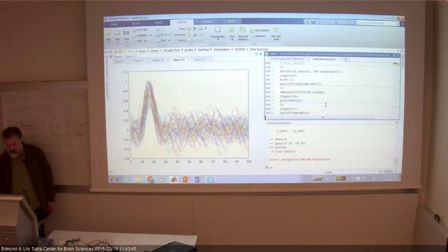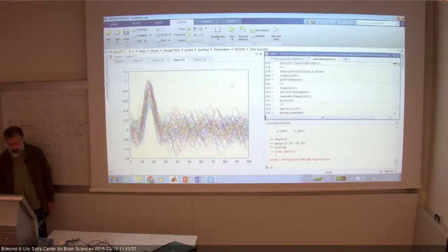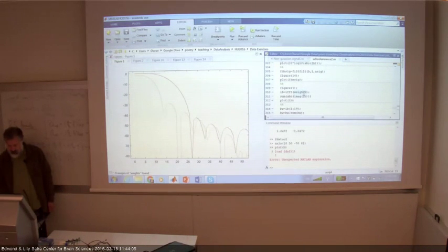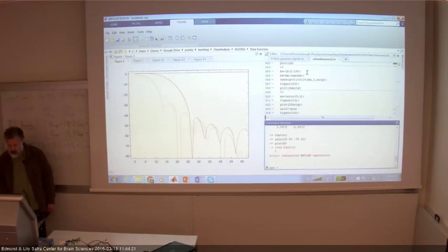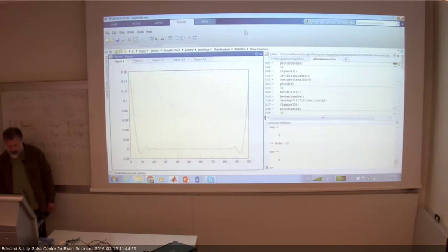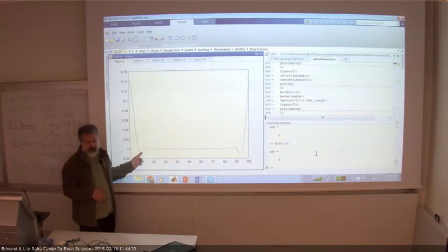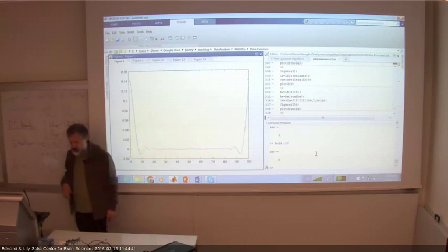Yeah, that's right. The last thing that I asked you to do was actually use the weights, inverse Fourier transform them, and get the impulse response. What is the impulse response that is implied by the yellow filter? I am using IFFT, inverse FFT. I'm checking that I get back a real signal, so I sum the absolute value of the imaginary parts. And I get this. Now remember, the reason that this looks funny is because it's zero phase. In order to really see the right shape, I need to use FFT shift to put the peak of the impulse response in the middle.